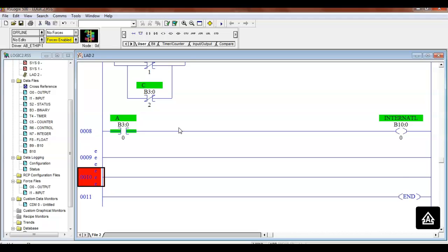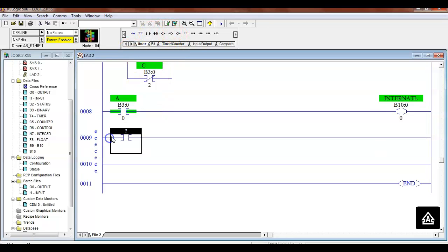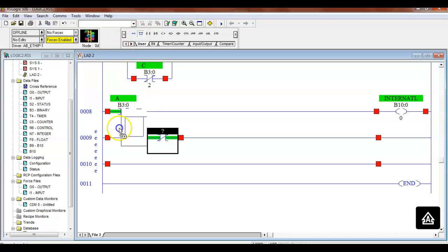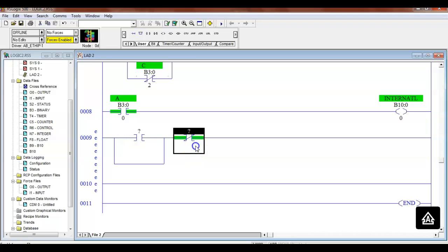If you know your program's got 5 rungs, you can just highlight one, insert 1 rung, and then after that you can just keep clicking on it, and it automatically sticks them in there for you. And what we'll do is we're going to come down here and we'll start off with this. And I'm going to put a down drop and pull this one in here and this one. So y'all understand down drops now. Are you okay on that, right?